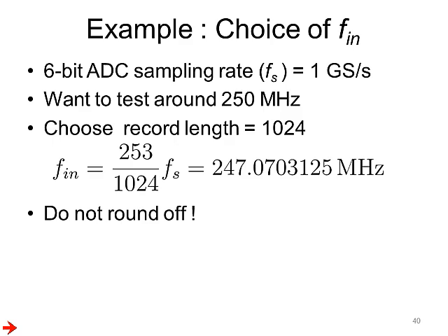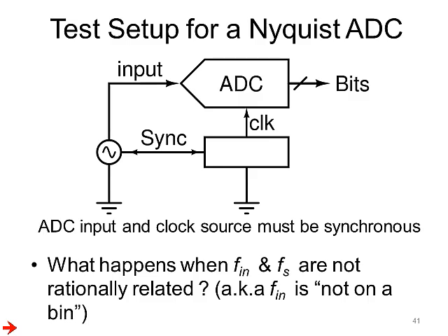And this also, I don't know how many of you have got a chance to take a look at ADC data sheets. If you look at the output spectrum, you will see the input being some strange frequency like 247.07 blah blah megahertz, right? And the reason for choosing that is to get M and P to be relatively prime. So if you wanted to test an A to D converter, you would make the input and the clock be in sync,